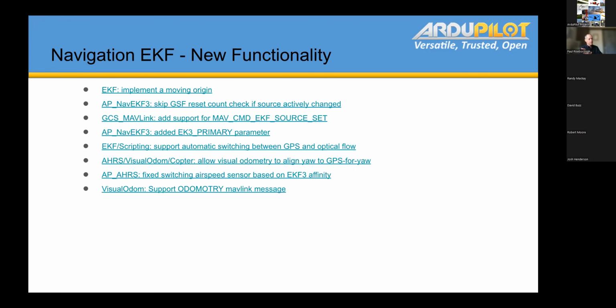Having said that, we don't do round Earth navigation. It's still a local north-east-down navigation frame for our EKF. And I don't think any of our libraries for our vehicle types are currently doing round Earth navigation. So if you want to do round Earth navigation, you still have to effectively put in a series of intermediate waypoints to achieve that.